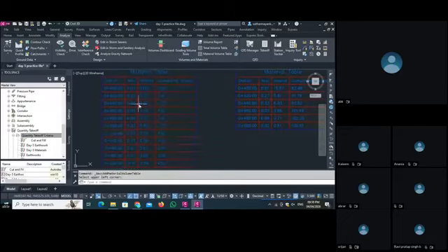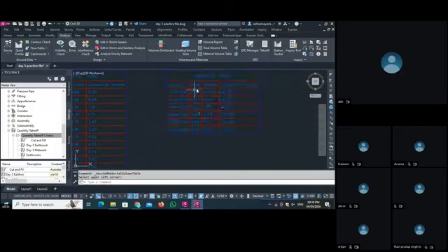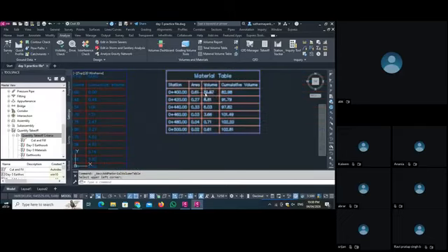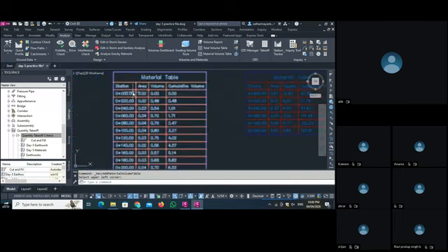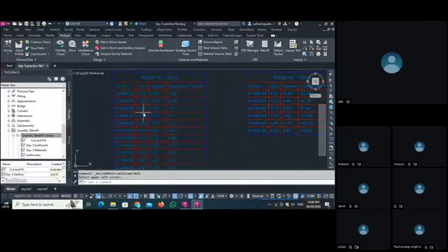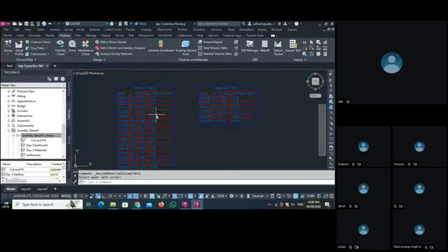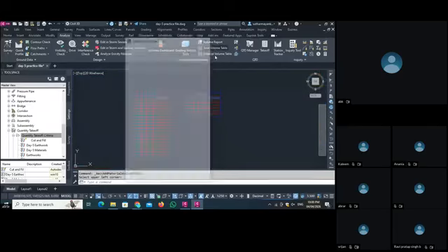So for each chainage, all the material data you can see here: all the volume of material you use at each station, what is the area used, what is the volume used, and the cumulative volume they use in total. Again, you can select the volume table.